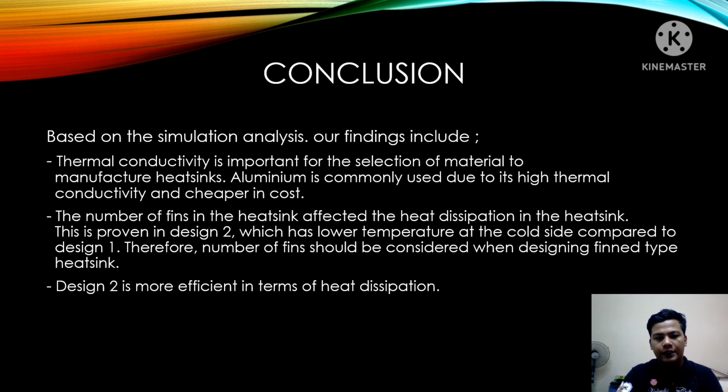This is proven in design 2, which has a lower temperature at the cold side compared to design 1. Therefore, the number of fins should be considered when designing a fin type heatsink. Design number 2 is more efficient in terms of heat dissipation. That's all for me. Thank you.